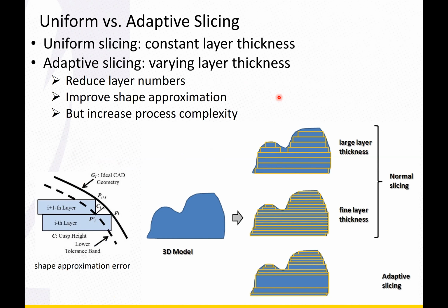Let me ask you a question here. So they were trying to do this adaptive slicing. But is it really that they're trying to print with different thickness sizes, or they're just trying to reduce the computational overhead of performing the slicing operations? I think the savings are in both ways. So you have fewer layers, then you have less computation for the intersection, and also more importantly, the people who develop this algorithm are expecting to have a better approximation in fewer layers.